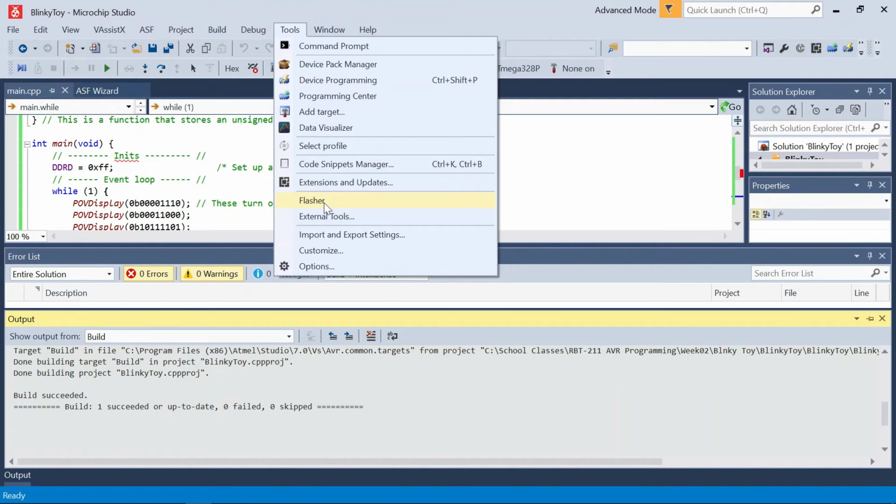we're using register D, okay? And on register D, the Arduino Uno version 3 shares its transmit and receive pins with output pins 0 and 1 on register D. So when you go to upload this to your chip, if you have wires plugged in, say you're using 0 and 1, and you have those plugged into your breadboard, or you have them plugged into your transmit and receive, it's not going to work.